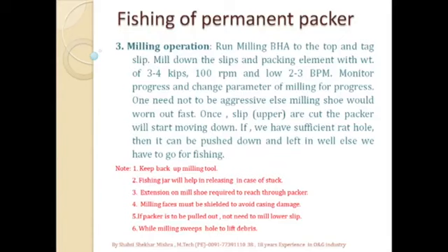Once the shoe is on the slip itself, we increase some weight, and normally we keep a weight of 3 to 4 kgs at 100 rpm and a low rate of pumping, 2 to 3 bpm, and we continue the milling, and at the same time we observe the progress, and based on the progress we change the milling parameters.